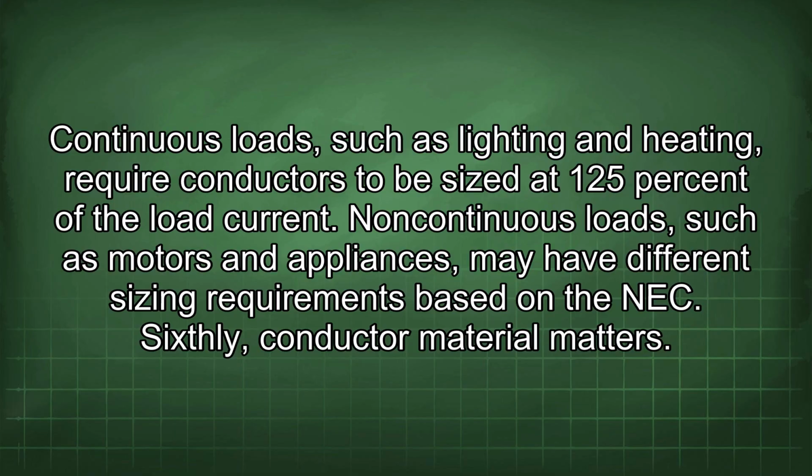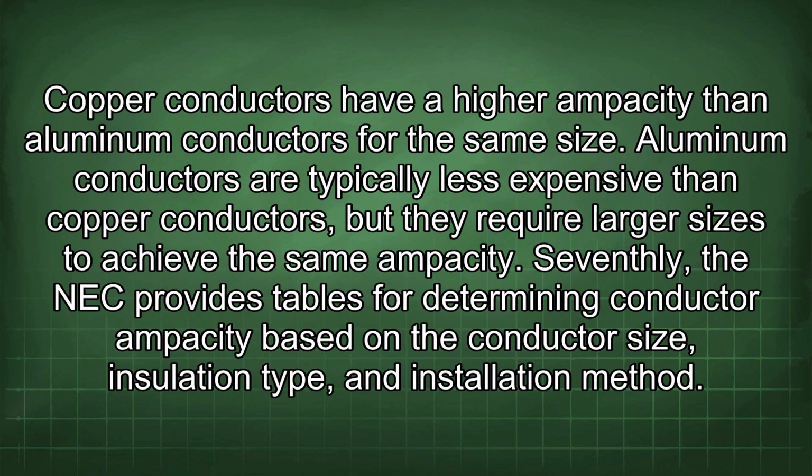Sixthly, conductor material matters. Copper conductors have a higher ampacity than aluminum conductors for the same size. Aluminum conductors are typically less expensive than copper conductors, but they require larger sizes to achieve the same ampacity.